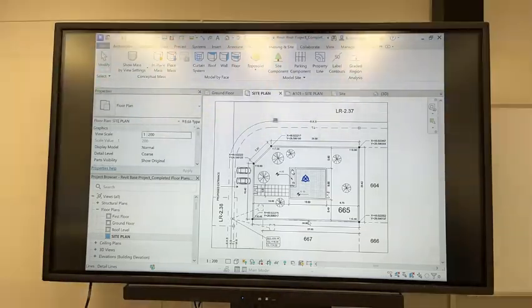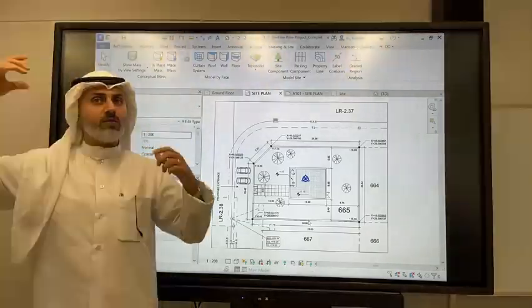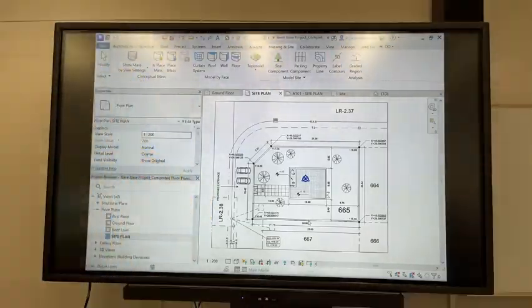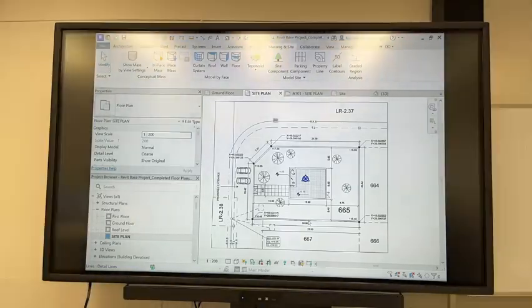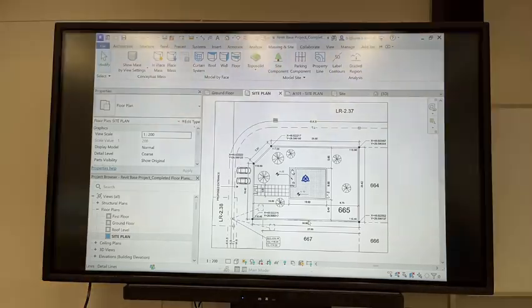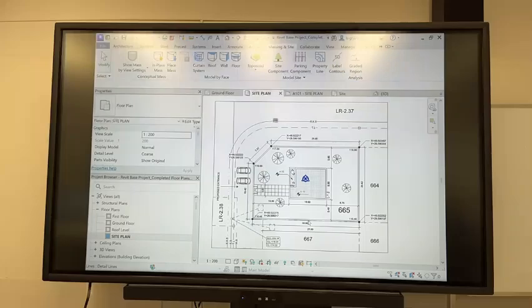There's a couple things. You can either do a thin line, or something invisible, and you offset it from the edge. When you draw the sand region, you might get the invisible lines overlapping the foot. So there are 2 ways. Either you do thin lines with a masking region for the sand, which is the right way, or you make the lines thin so the line shows, or you make them invisible but offset from the edges. That's like a thin, clear border, so it's not overlapping the data. Otherwise, your masking region is going to cover the information.